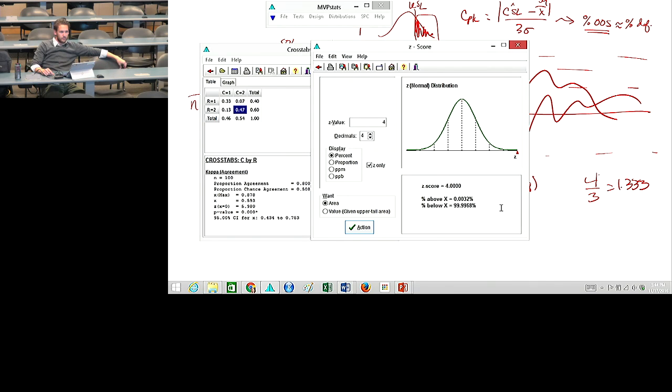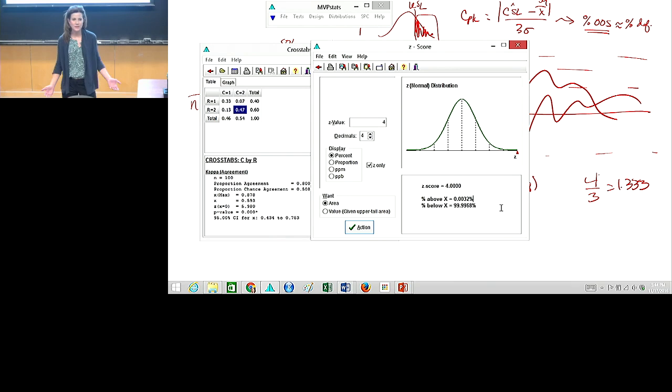I just put P down. You could use either one. And you know from your flow chart that either one is fine. Some people relate better to counts. Some people relate better to proportions. So if you have equal sample sizes, then that's fantastic. It's been my experience that I never had equal sample sizes when I was doing proportion defective in manufacturing. Never. So I never got to use an NP chart, but I would have really liked to.